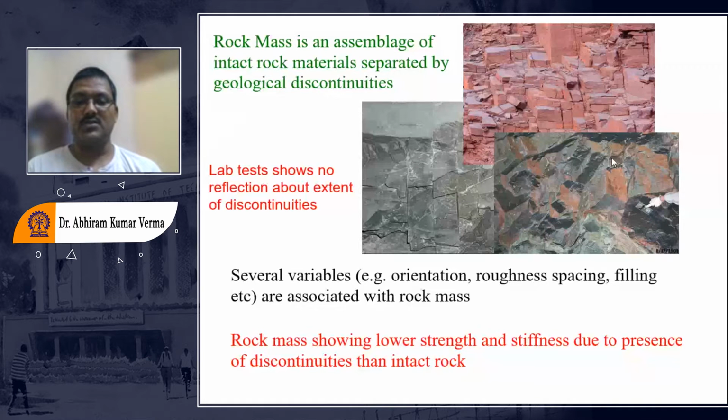Whereas in this figure also, again you will see that similar to that, the failure of these rock pieces is happening on a particular orientation, but you can see this joint is much more compact in comparison to what we are seeing over here. But other observations are there. There is maybe a presence of some different orientations of joints, which are very orthogonal in nature, but those joints are not open at all.